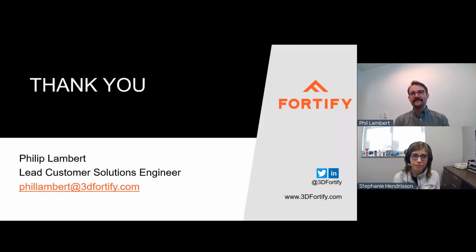Beyond that, right? Viscosity, as I talked about, isn't the only metric of rheology that plays a role here. There's a shear thinning aspect to your resin. We can even go to higher room temperature viscosities, and by introducing shear, we can leverage that behavior to 3D print that material. So I'm sorry that wasn't a fully straight answer, but there are some nuances to that question that I wanted to touch on. So thank you for the question.